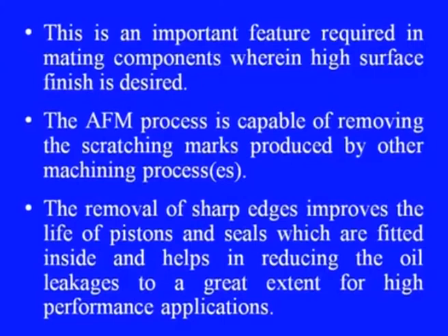The removal of sharp edges improves the life of pistons and seals which are fitted inside and helps in reducing the oil leakages to a great extent for high performance applications. This also can be achieved by finishing a part to a very close tolerance.